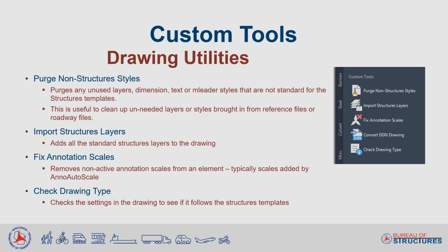The Import Structures Layers tool will add all standard layers to the drawing. Fix Annotation Scales will remove all annotation scales except the currently active scale from the selected elements. Check Drawing Type will check the drawing's settings and let you know if they follow the Structures template files.